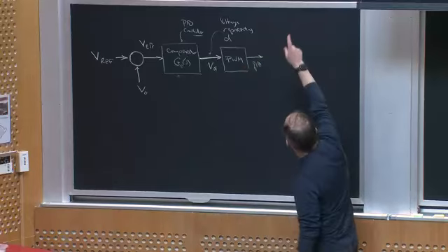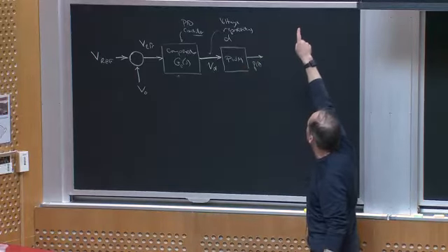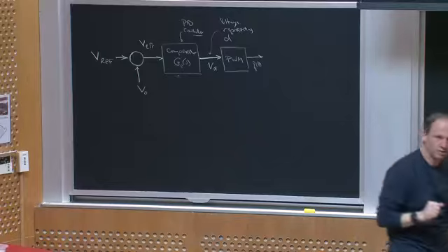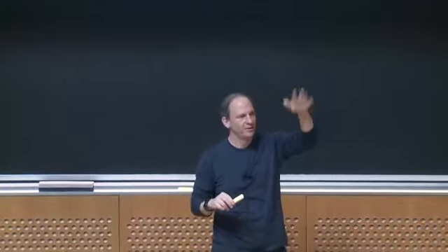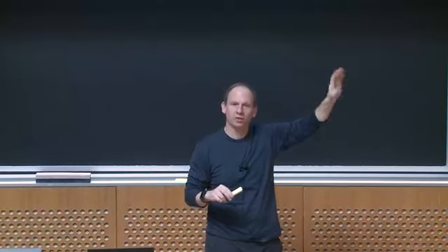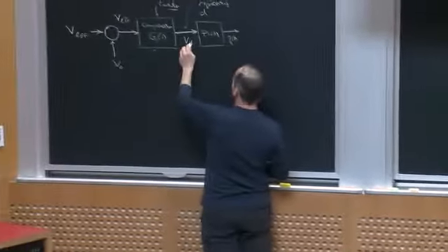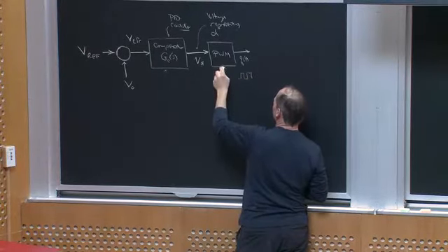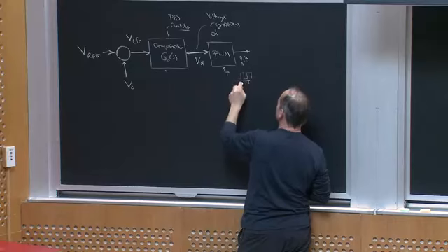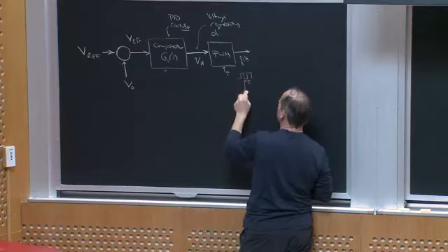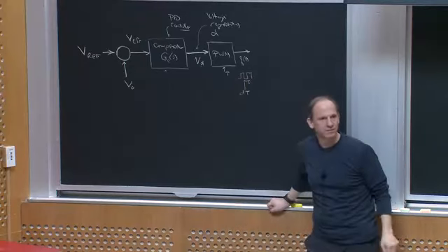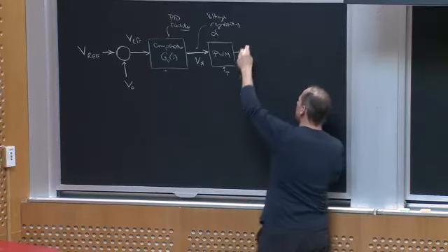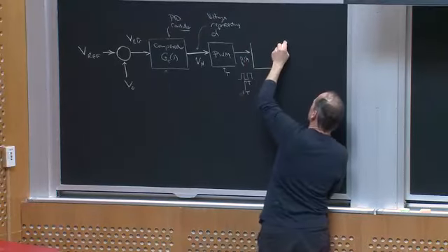Right? Because if I look up there, I'm talking in terms of duty ratio, but the actual signal going to my switch is some q(t), or some amplified version of q(t) from a gate drive that's turning the switch on and off at the right duty ratio. So the input of this is the value of duty ratio I want. The output of this is some PWM waveform switching at period T with an on time that's DT. Okay? This then goes into my actual converter.